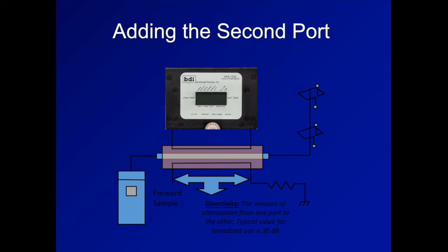It's the same thing with RF. And here's a typical example of what I'm talking about. There are a lot of words on this page, so I'll try to explain this. AM noise, this is something that used to be very, very critical with vacuum tube transmitters. Maybe not so much anymore with solid state because they're fairly broadband, but you still do want to know what the bandwidth, let's say, of a filter is, or the antenna itself. You want to make sure that nothing between the transmitter and the load is impeding your signal, and that it's symmetrical. And that's what AM noise allows you to do, to measure that on an FM system, for example.